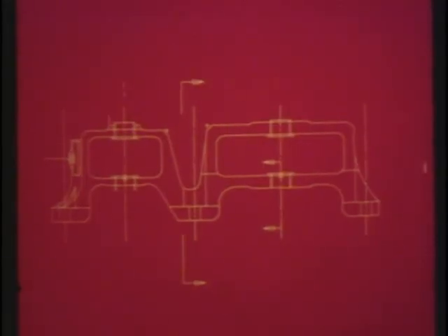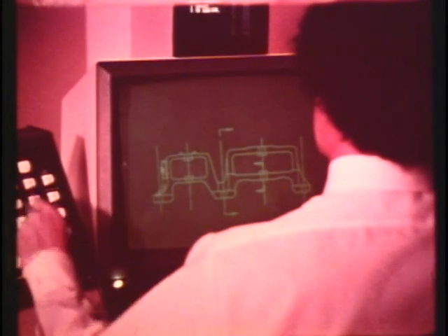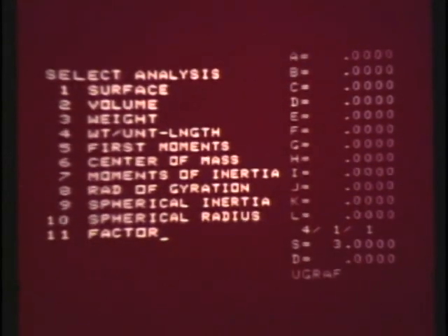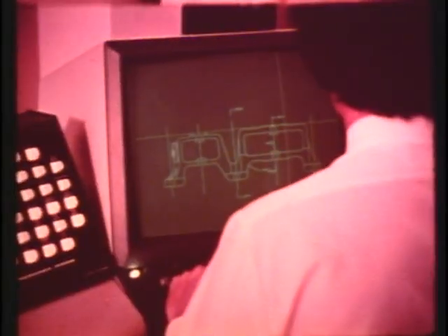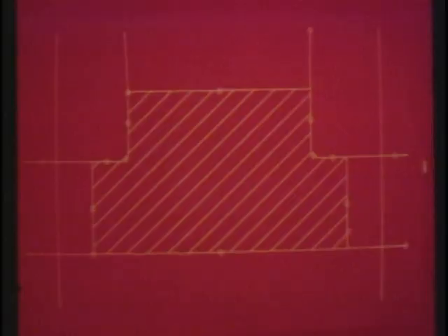When the drawing is complete, it is checked. This analysis and verification of the geometry is another push-button operation. The drawing is then detailed with the addition of dimensions, labels, notes, and cross-hatching, again, interactively.